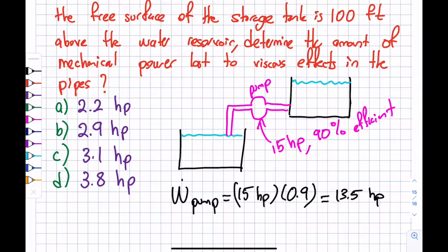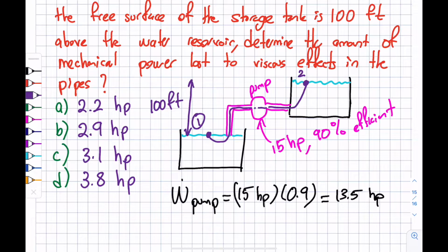So all right, fine. Here's the thing. What I want to do here is to see actually how much of this power goes to take a fluid, let's say it was here, and then suck it over here, continue through here, and just go into there. Okay, let's say point 1 to point 2. Actually, this I forgot to tell you, but this is 100 foot that is given in the question statement. Okay, so let's look at this energy change of this particular streamline. Let's take a look at this streamline going from 1 to 2.